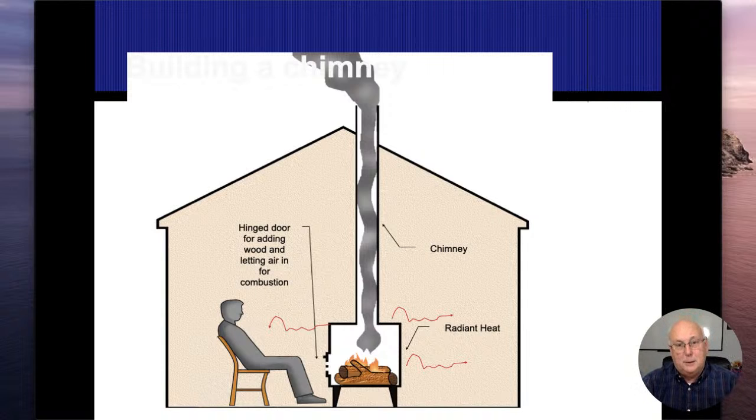So if we break it down to the bare bones minimum, and we take this wood stove, in all reality, this is what we would refer to as our heat exchanger. All right. So I have a fire inside the wood stove, or inside that heat exchanger. That fire gets the metal of the wood stove, or the metal of the heat exchanger, extremely hot. That heat now is going to start heating up the fresh air, the clean air that I breathe.